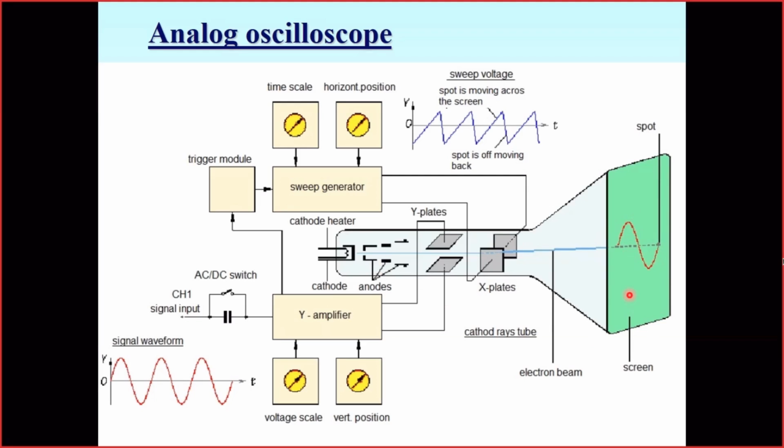That's why very often the screen and anodes are grounded, and the cathode is under a high negative potential, so it repulses the electrons produced on the cathode towards the anodes. From the electricity point of view, it's absolutely the same situation whether we put 0 voltage to the cathode and plus to the anode, or 0 to the anode and minus to the cathode. The potential difference will be the same.